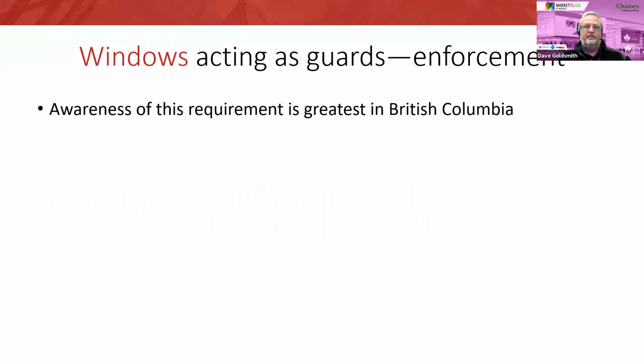And it is possible for a safety codes officer on a Part 9 building to demand a design according to parts 4 and 5. If they notice that it's on the top of a hill or escarpment in a high wind area, it is within their authority to say, no, standard Part 9 conditions are not going to be sufficient for this building. I need some engineering done. Right. So in other words, even outside of yourself, a building official may require engineering for some condition that would then involve you in having to be fully compliant with these Part 4 requirements as well.